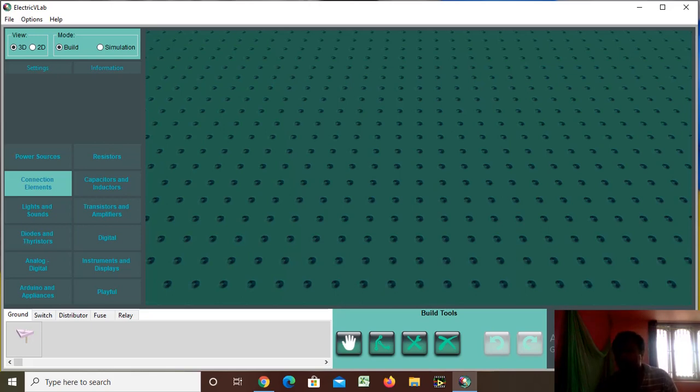PIV is very, very important. PIV, the peak inverse voltage, refers to the maximum reverse voltage during the reverse biasing condition of a diode. So that is what we call PIV. Always remember, while designing any rectifier circuit, this PIV should be small so that the diode can withstand it. If PIV is more, the diode will not withstand and will become damaged. In a full-wave rectifier, PIV is very large, and that is the reason why we avoid the full-wave rectifier.